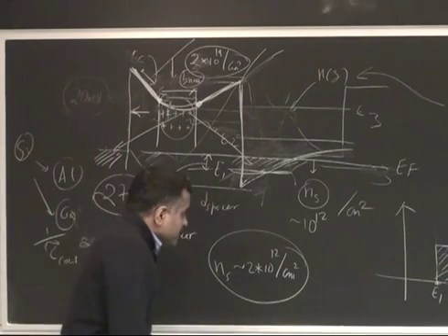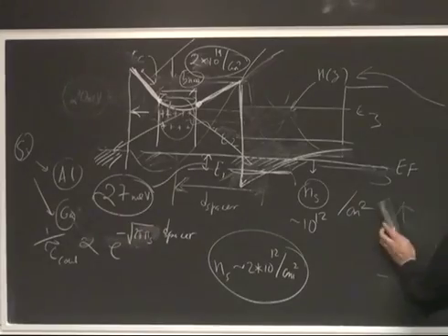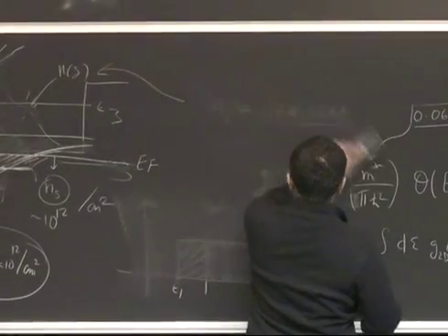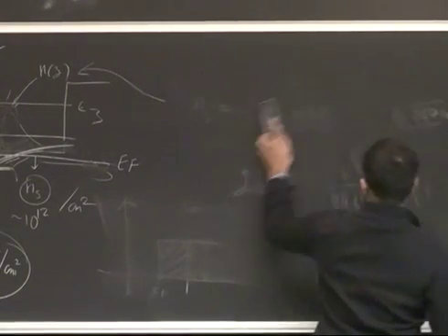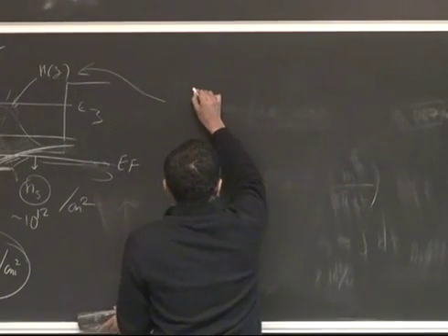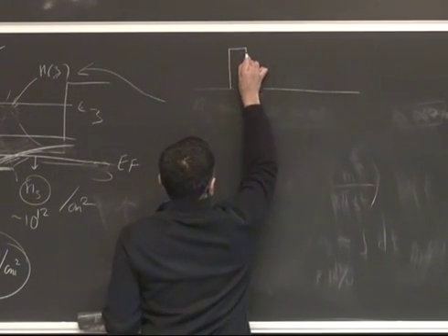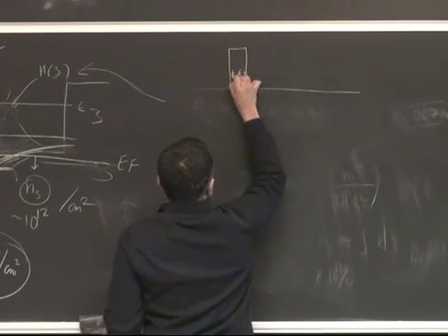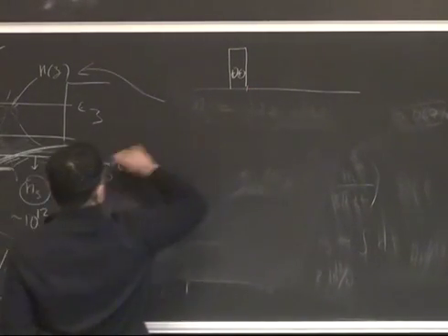So after all this transfer has happened, your band diagram, the charges and the fields will be connected in this way. Let's look at the charges. We have positive ionized donors in this 5 nanometer modulation dopant region.